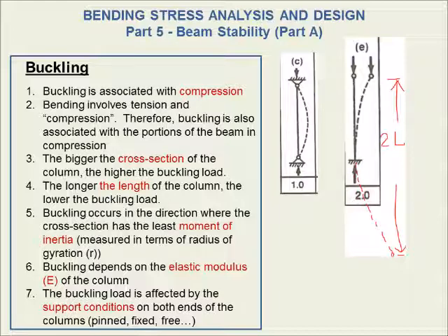If you see here what I have drawn out in red to join the black dotted line, it is bending as though it were twice its length. It is essentially behaving as though it were twice as long as the pinned column. Hence, this column will be 4 times as weak in buckling.